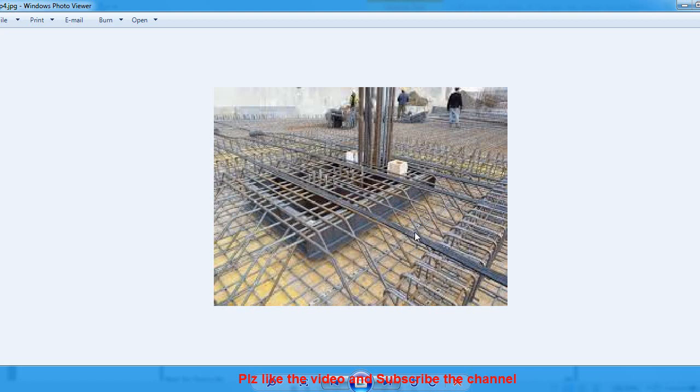These I beams and bent-up bars control the crack, and similarly further they provide beams as well. So the key function of this kind of arrangement, similarly you see, is that prestress bars are also provided. When you have a high amount of punching shear, basically we do this kind of arrangement.